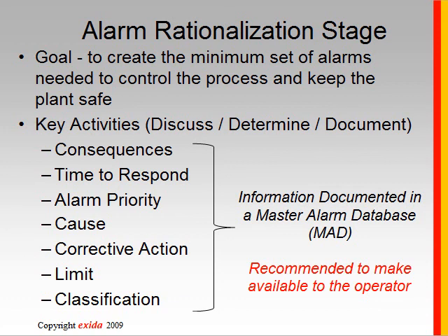In rationalization, the goal is really to create the minimum set of alarms that are needed to control the process and keep the plant safe. Again, more is not better. We just want the most significant and most necessary points.